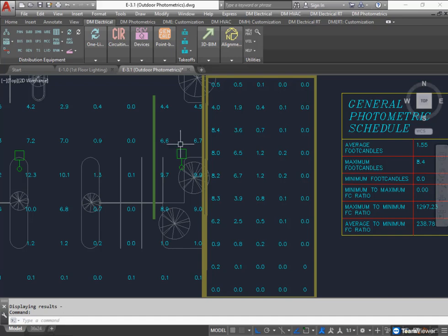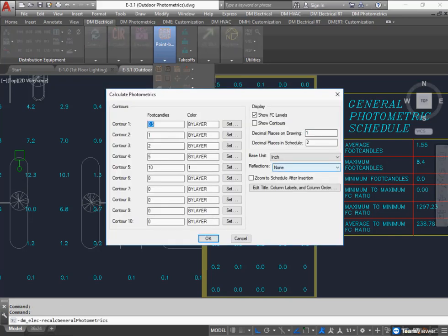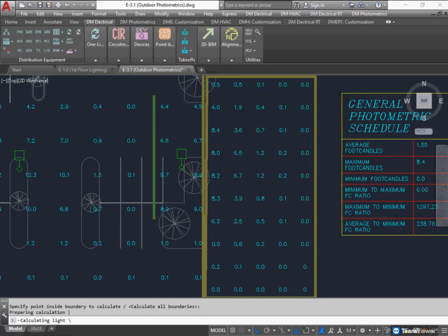So that's the numbers we're getting. I just wanted to make sure that we're seeing the right value. I didn't know how much this light was going to impact it, because now that light fixture is not shining because the wall is blocking it. Turn on the single reflection, click OK, run the calculation, and you see that that 9.7 went up to 17.7. So you've got this wall right next to the light fixture. It's reflecting a fair amount of light, so your numbers are going up.